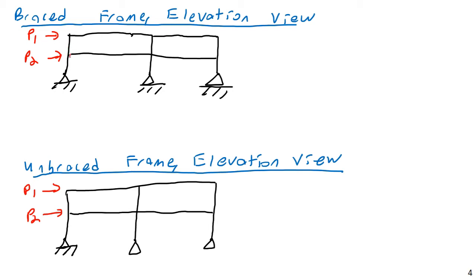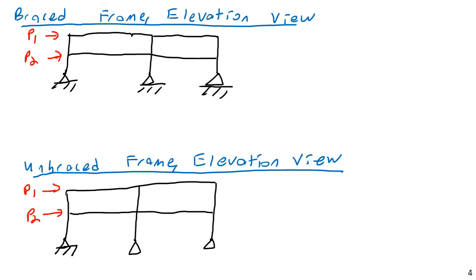So where would these point loads come from? Fundamentally, imagine where the cladding of a building meets its floor slab. When I say cladding, in a house it could be something like siding or brick, or in a taller building it could be the windows. If you have a large glass skyscraper, it would be the big window panels all the way along. Whatever the facing material of a building is, that load doesn't get carried all the way to the foundation, except maybe in a very short building, but it doesn't get carried all the way to the foundation via the actual paneling.